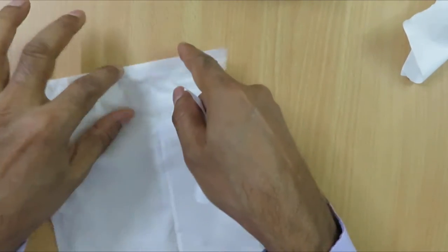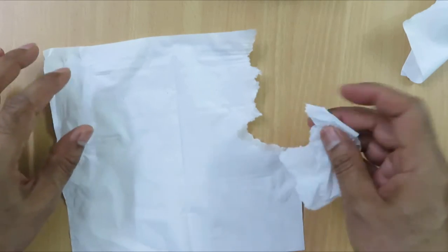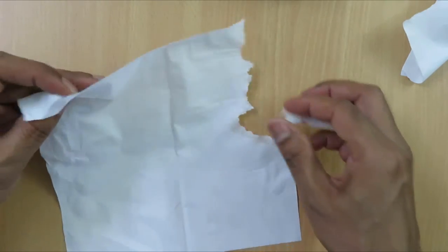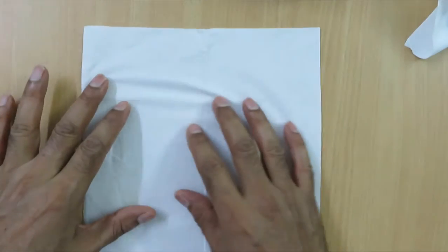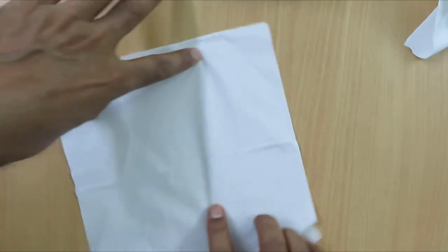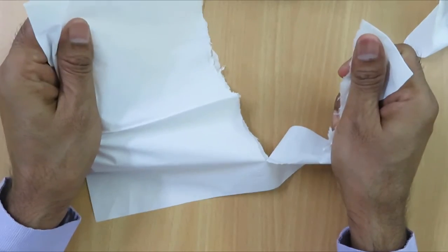But this crack can never go straight. It always gets diverted, and because of this it consumes a lot of energy and force, and therefore this is stronger in this direction. But in a transverse direction, if you see, so this is longitudinal direction, I turn it like this. In transverse direction it will be easier.